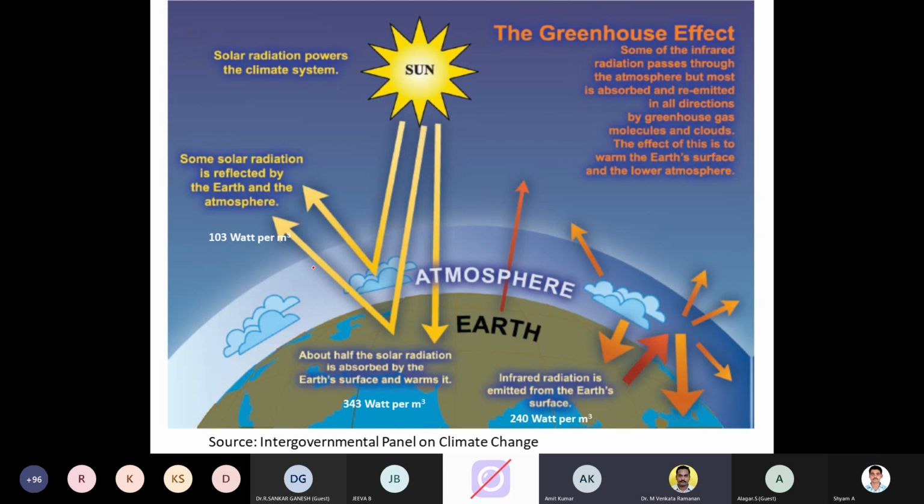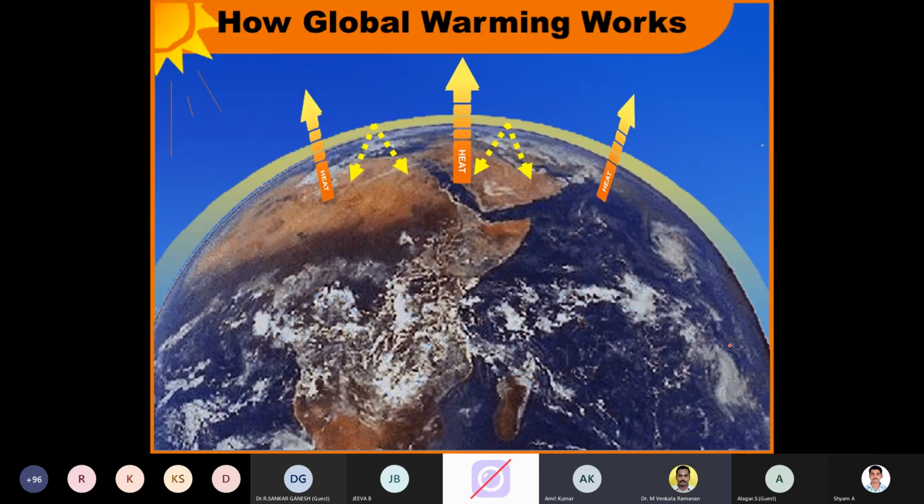Probably the atmosphere will have CO2, whatever we have from the hydrocarbons, whatever fuel that we have, all are hydrocarbons. So the carbon content upon oxidation, carbon plus oxygen, will give an abundant amount of heat energy, carbon dioxide, and it's an exothermic process. Approximately 8,800 kilocalories of heat energy would be available for every kg. So much heat energy would be available, and this carbon dioxide will be settling in the atmosphere. It will have the same effect as the